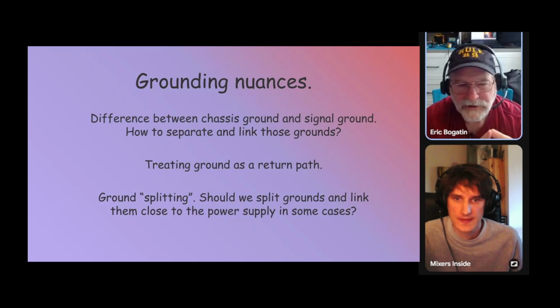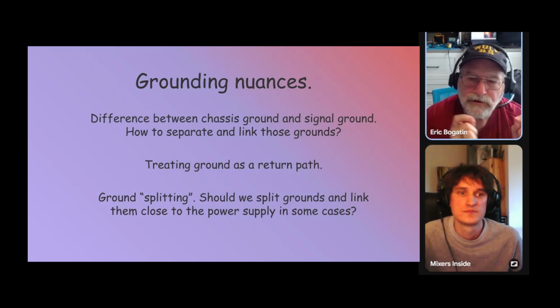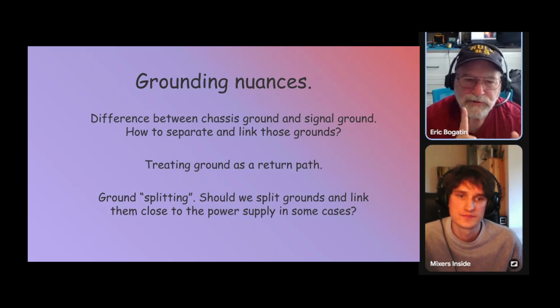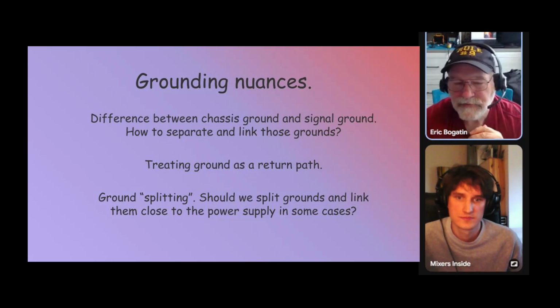We're not going to drive a lot of current in that line, but we don't have any of the return currents flowing through that will drive crosstalk between some noisy source and the reference.